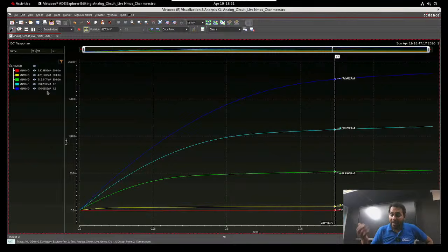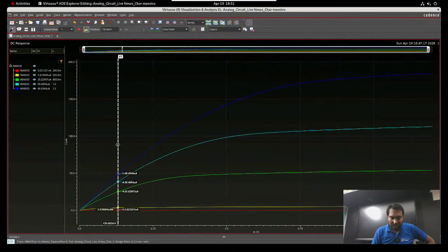Just like transmitting data. So that is why the amplifier is important, and why the saturation region is important. If you look at the same thing in the linear region, at 200 millivolt it is 3 nano. At 500 millivolt it is 3.4.